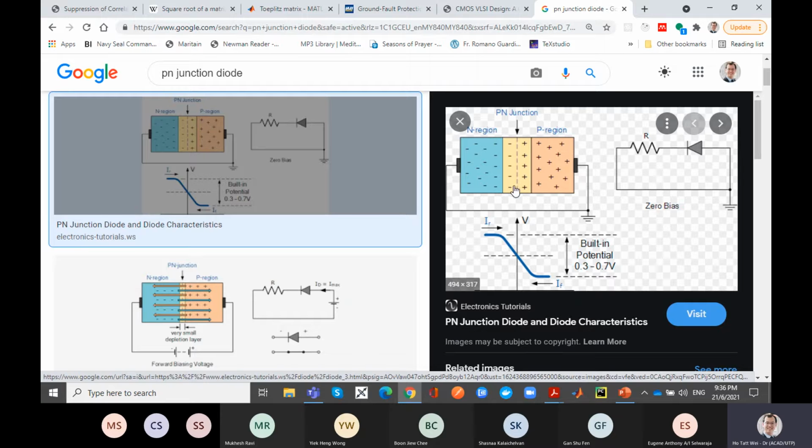So when you reach, let's say, 0.7 volt for a silicon diode, it means that this region here has its negative charge restored. This region here has positive charge restored. If you remove the 0.7 volts for silicon, then there is a reverse bias here. Why? Because all the electrons go here, all the holes go here, and this region has no free carriers or very little. So what happens when you have a conducting layer, a conducting layer, and a layer without conductance? There is a capacitance across the diode.